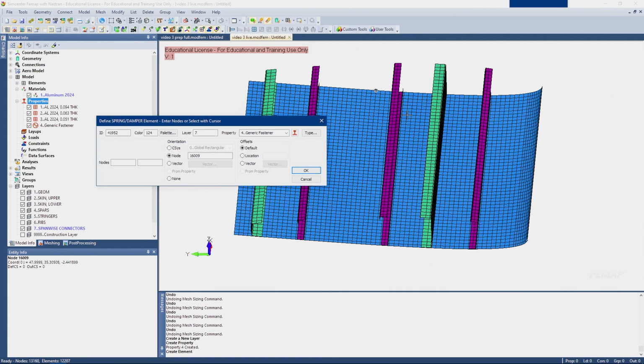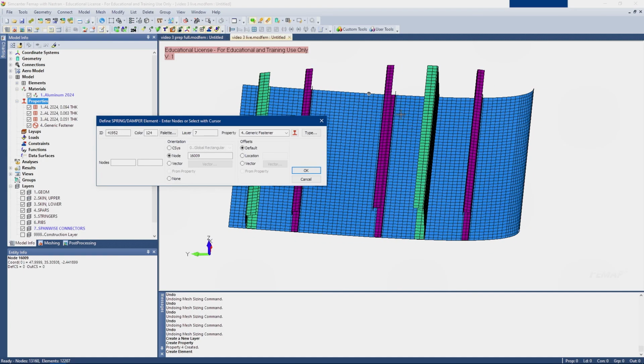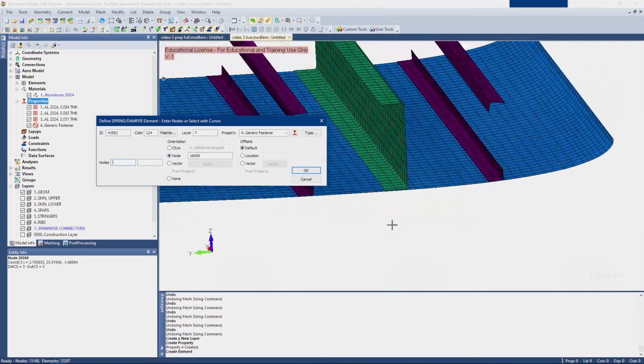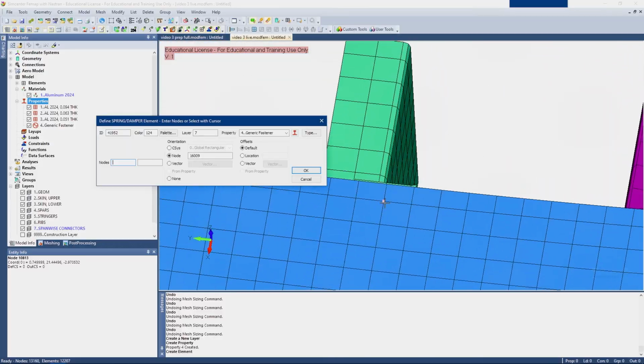Essentially it'll just snap the vector to that plane. So basically, for a bolted joint that has lateral stiffness the same in all directions, you can just select whatever node you want as long as it's not on the axis of the bolt. So we're just going to select that one. And let's go ahead and start modeling.